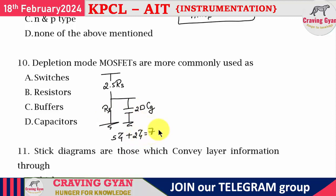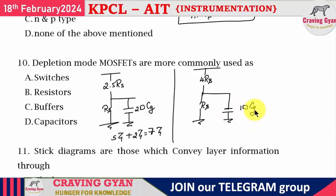Strictly speaking, here we are going to make use of two similar CMOS logic, and then we have to derive the delay. But in the case of NMOS, the pull-up network will be having a resistance of 4 RS, and the pull-down will be having a resistance of just RS. The load will be 1 square Cg, because only one capacitance needs to be driven. But in the case of CMOS, 2 capacitors should be driven. So pull up 4 tau, pull down 1 tau, which is 5 tau. So these things are representing resistors. Option B is going to follow.